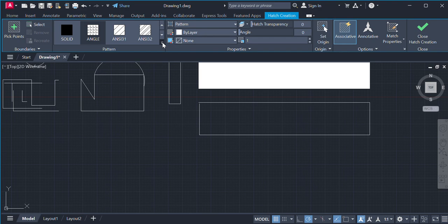Remember, even in drawing 1 or EGD 1, you had sectioning where you would cut it in a specific direction and show essentially the material that's been cut or the parts that have been cut. We use ANSI 32 for your walls, then you use concrete for concrete or your foundations, then you would use the earthworks one to show the soil below ground.